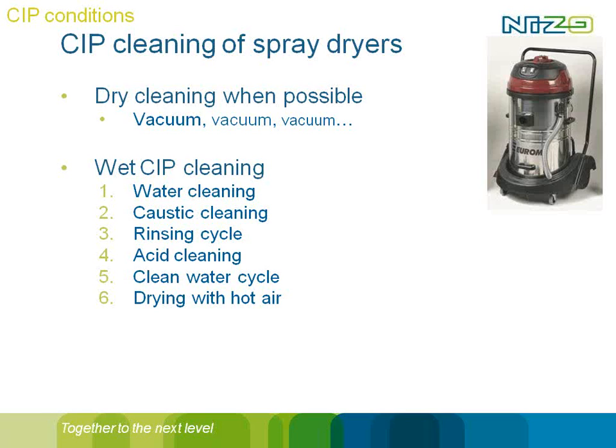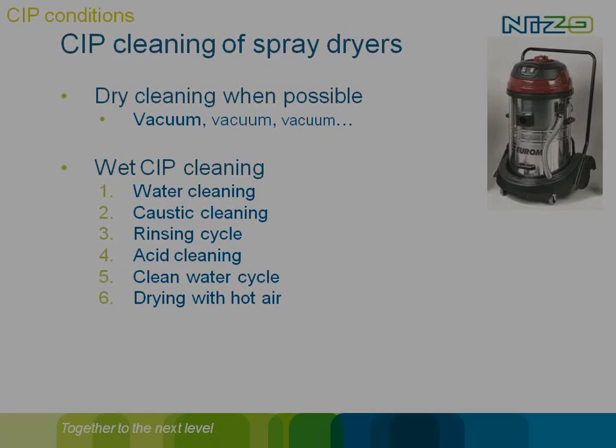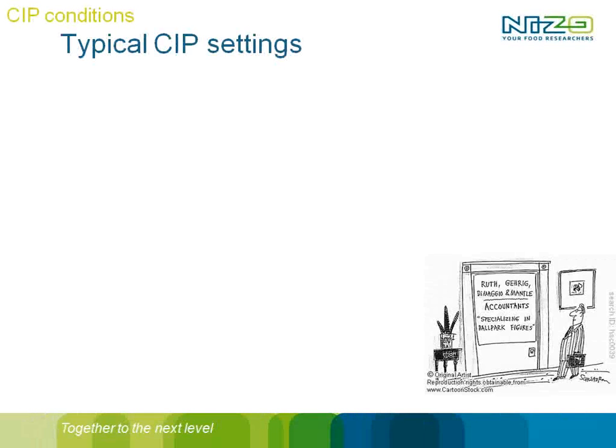extra growth of bacteria, because powder does contain bacteria that can start growing as soon as water is available. So it's very important, looking at salmonella, looking at spores, to get rid of this water in order to get control over your possible risk of outgrowth in powder. So if you can prevent the wet cleaning, do. If not, in that case, dry at the end of the procedure.